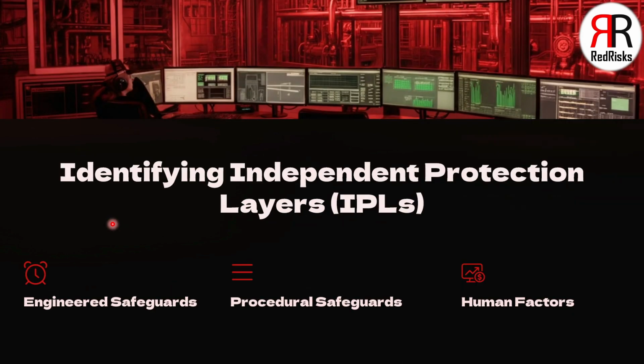When we think about identifying independent protection layers, IPLs, we're looking at automatic systems that are designed to detect and respond to hazardous conditions, such as pressure relief valves and emergency shutdown systems. Then there are written instructions, checklists, and protocols that guide personnel actions to mitigate risks and prevent incidents. When it comes to human factors, we think about proper training, competence, and situational awareness of operators and other personnel to recognize and respond to hazards. In terms of identifying IPLs, we can go toward looking at engineering safeguards, procedural safeguards, and also human factors.